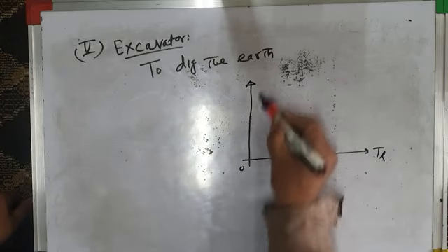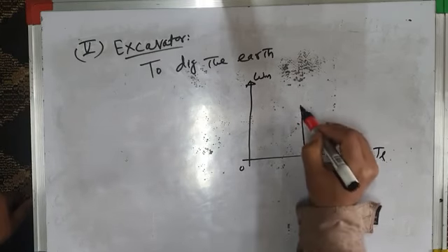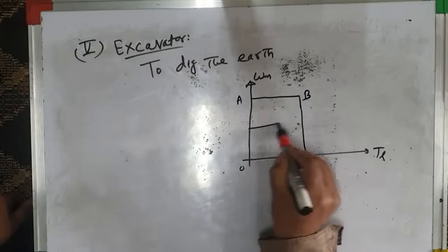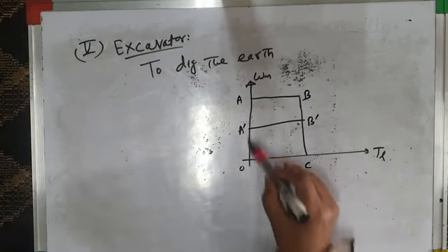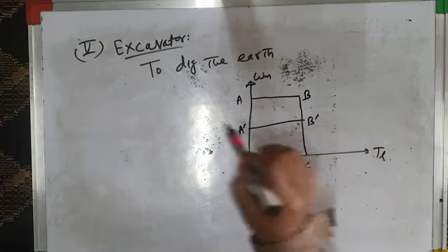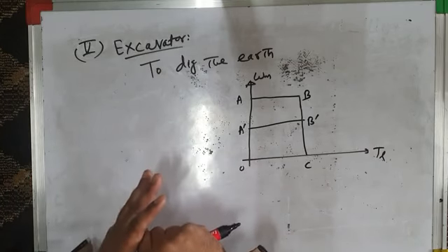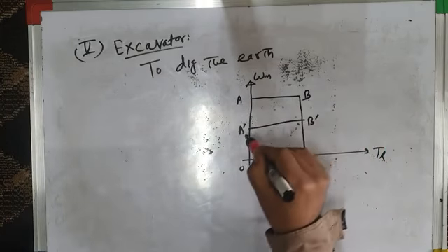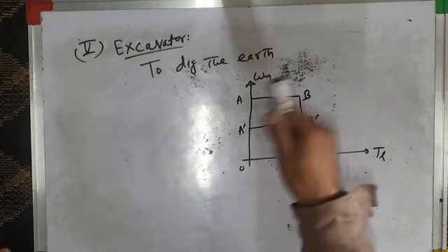This is the load torque and this is the speed omega m. It should have this type of characteristic. This is A, B, C. This is A dash, B dash. You see initially the torque developed is this. As the speed increases, torque decreases. It does not remain constant. And it protects the excavator against damage when, during the digging process, it strikes a hard stone. So as the speed increases, the torque should decrease like this. This may be for one excavator, and this may be the characteristic for another excavator, or at different speed levels.